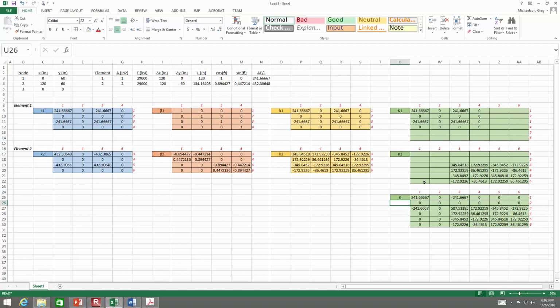We're not going to go into this today. I just want you to understand. What do I do from here? What do I do to this matrix? Strike out rows and columns, right? To get this central core right here. Okay? What do I then do? I have a force vector, 0 minus 10, get my displacements. Take my displacements, split them apart.